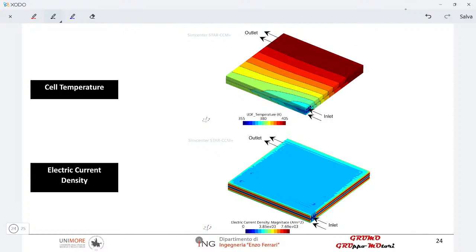And those pictures were related to the membrane, to the catalyst, I mean, on the membrane. And here is the cell temperature on the outside. I mean, clearly in this first picture, you see an extreme heat generation. I mean, here we are way above 100 Celsius degrees. So actually this fuel cell operates very badly because in all of this hot part towards the outlet, we expect to have a fully dehydrated membrane. I mean, the water can't stay in the membrane, okay?